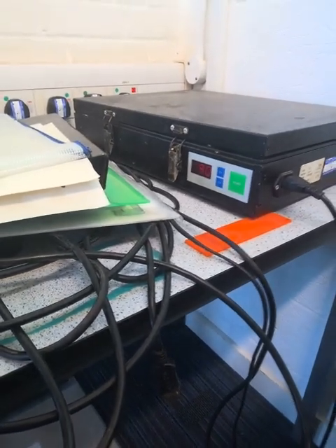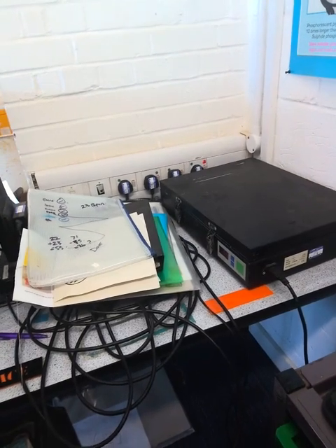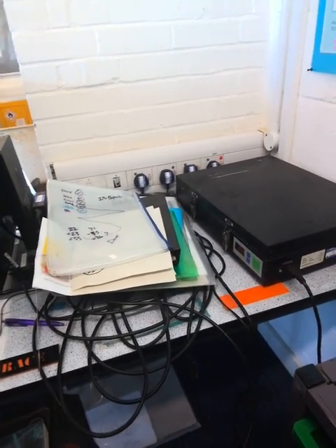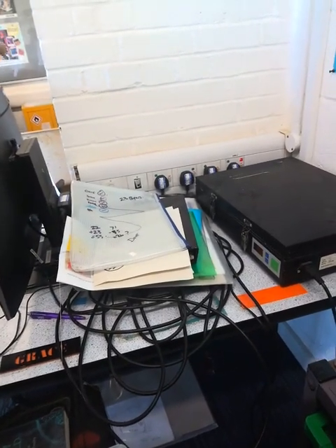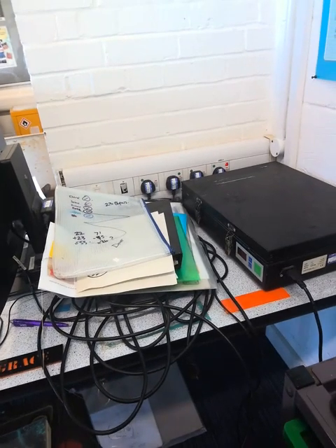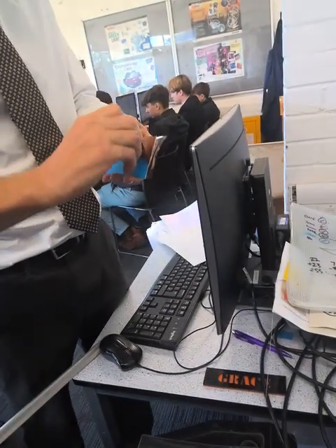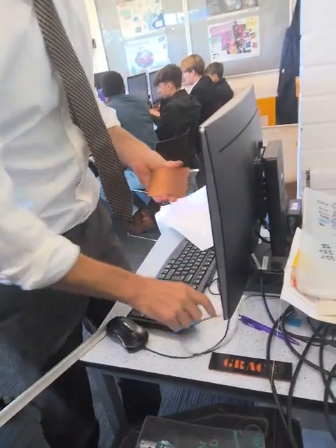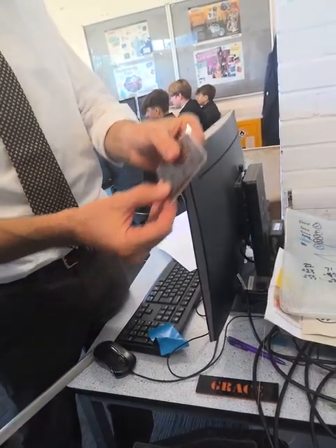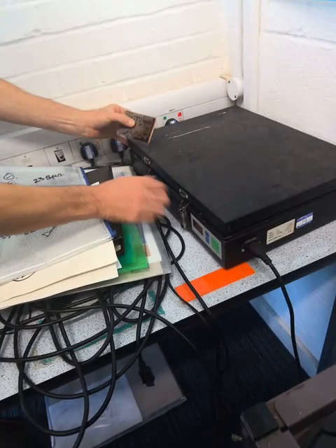The next thing we need to do is expose that image onto our piece of PCB. Now, you remember what I said? It's got a piece of glass fibre, then it's got a copper layer, then it's got that photoresist layer, and then it's got this blue layer, which is really opaque, which stops any light getting through. So what we're going to do is we're going to peel this off. We're going to place our mask on it, and so the writing is the right way round. It's really important. We're then going to open up.